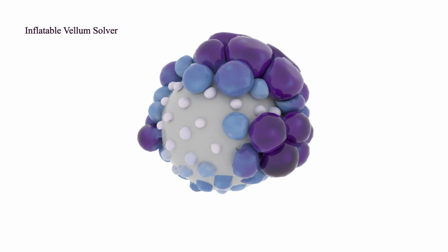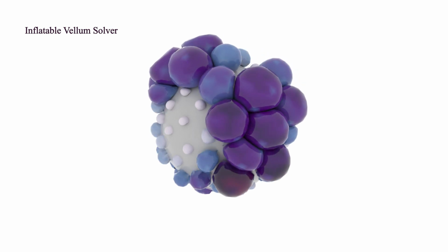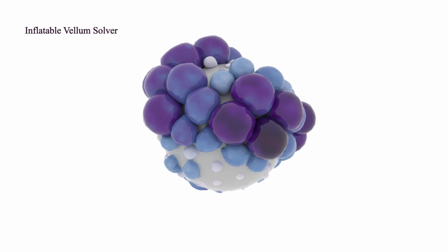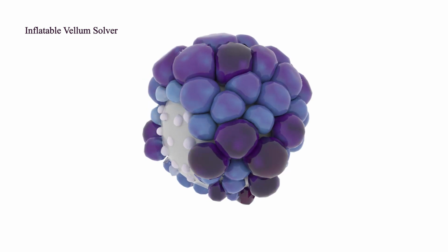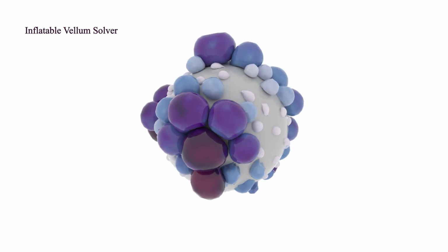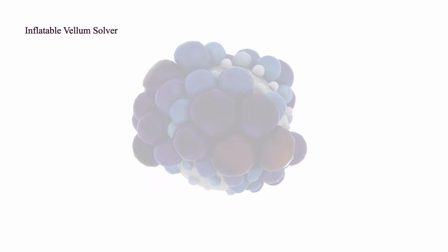By using an inflatable solver tool to simulate firstly an unconstrained inflatable body, I was able to learn and understand how to control the inflation parameters on diverse geometries. The different colours indicate the stress inflation to which the geometry is subjected to.